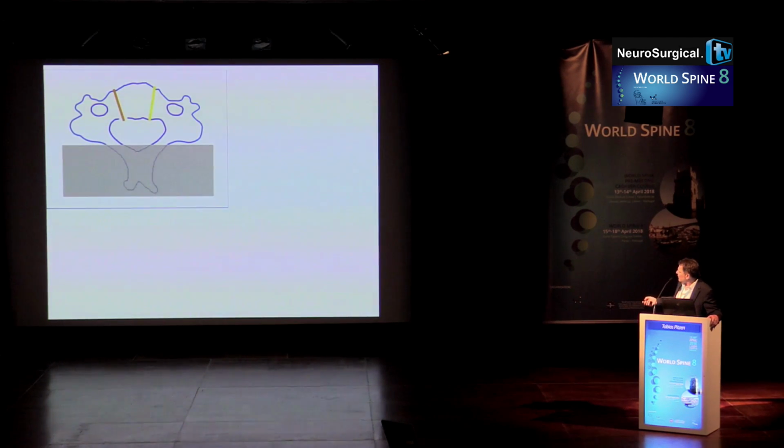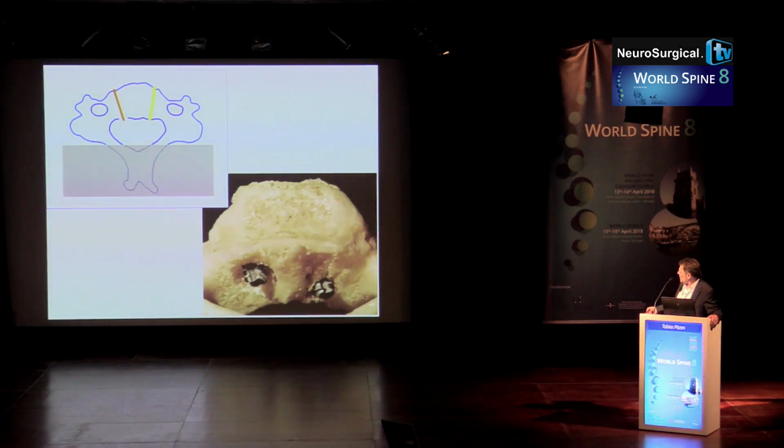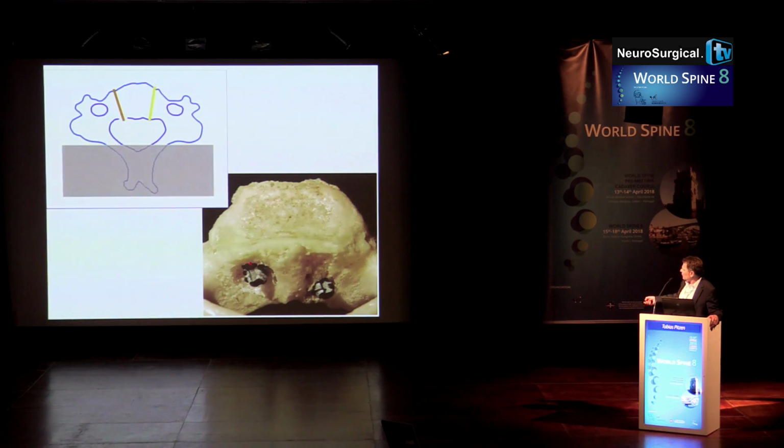I did embed the cervical vertebrae into PMMA here, and then I applied 2 drill holes as you do it in real surgery, and I removed the cortical shell in one and I left it in the other, and then I torqued, I fixed, or in the second trial, I pulled them out. So you can see one of the specimens, just to demonstrate what we did here. We took out the posterior cortical shell with the diamond drill here, so that the posterior cortical shell was taken out from the experiment.